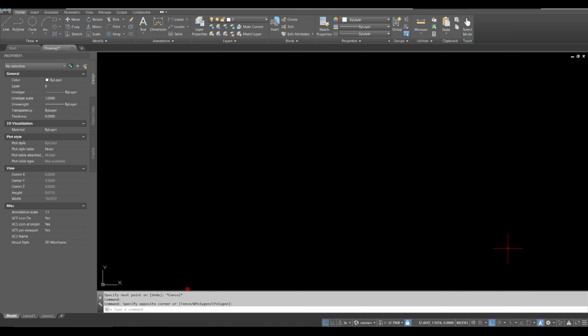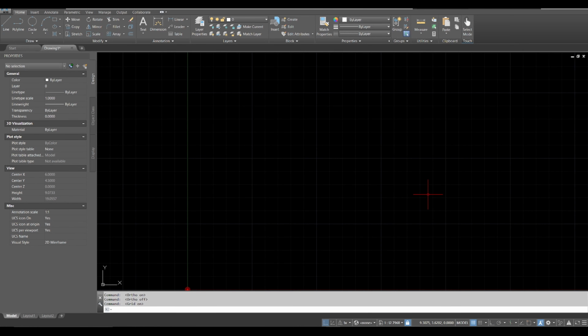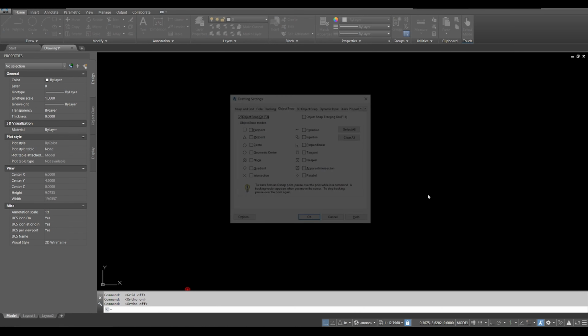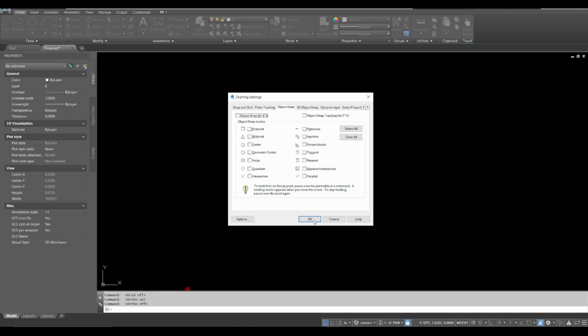Now, I'm not going to go over every single one of these. Just in this menu alone, there is a wealth of information. The main thing is you can see at a glance, hey, do I have ortho mode activated? You know, F8 for ortho mode, F7 for your grid. I mean, obviously you can see your grid in the background. But just things like that, right? Do I have my O snaps on, etc.